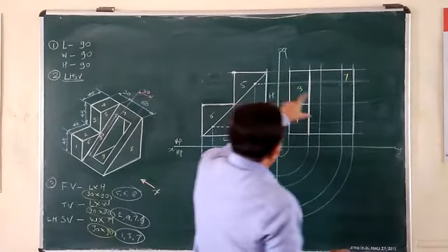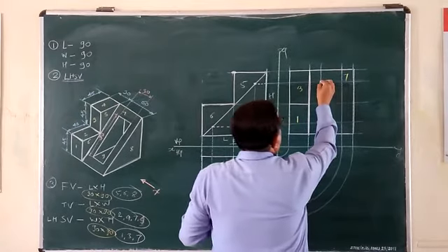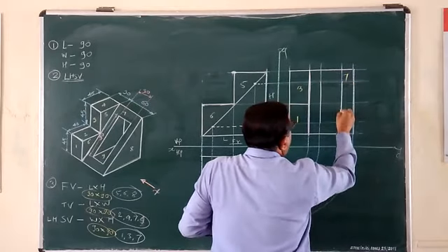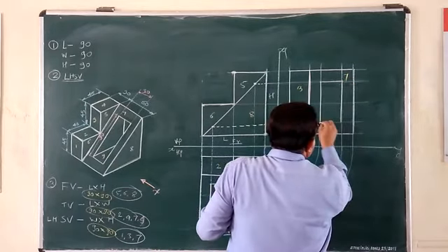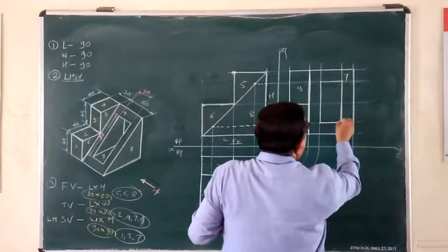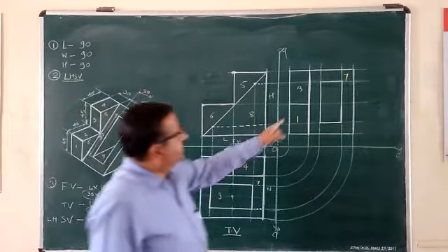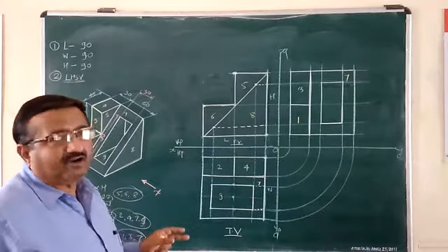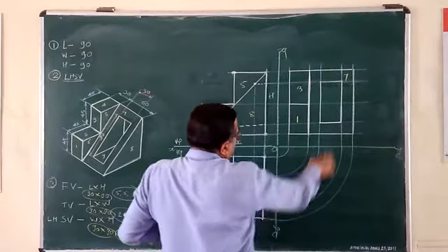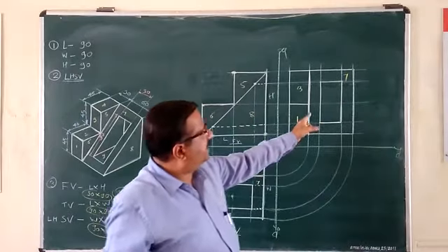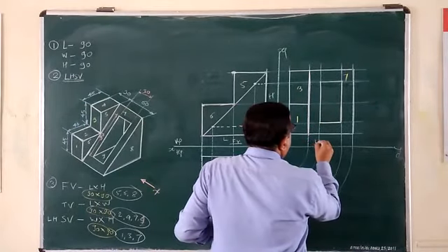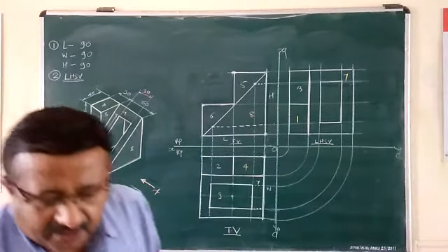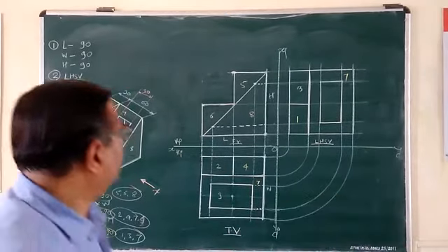This hole, with its size and shape, is also available to us. Automatically the cross projection lines have given us the desired location, shape and size of that hole. We haven't used any kind of scale here. We haven't measured at all. But only by getting the cross projection lines, this shape has been formed. This is nothing but its left hand side image, which is drawn right of the front image. So ultimately, only showing the dimensions is the left out part.